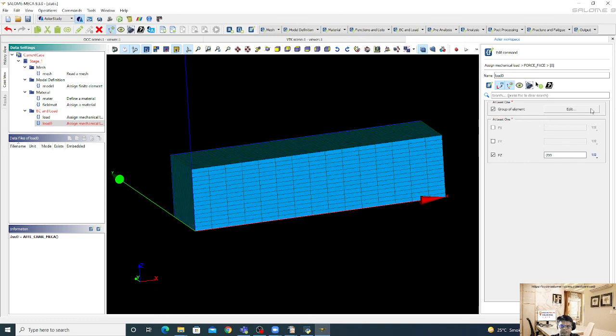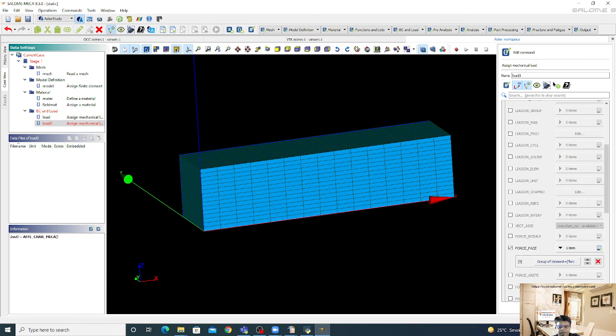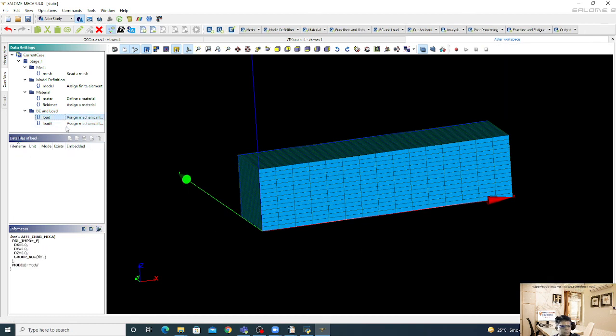Okay, because I haven't selected the group of element. Now the force. Remember that for this example I have not converted any units, even for Young's modulus. I have just inputted it in megapascal, whatever value I remembered I input. But while conducting the real time analysis for the actual part, we must make sure that the unit systems are consistent.